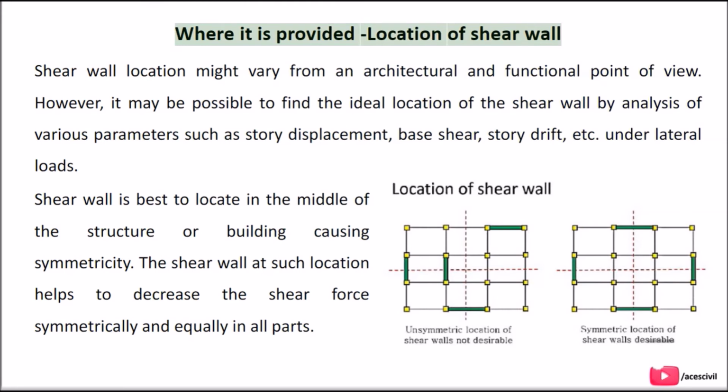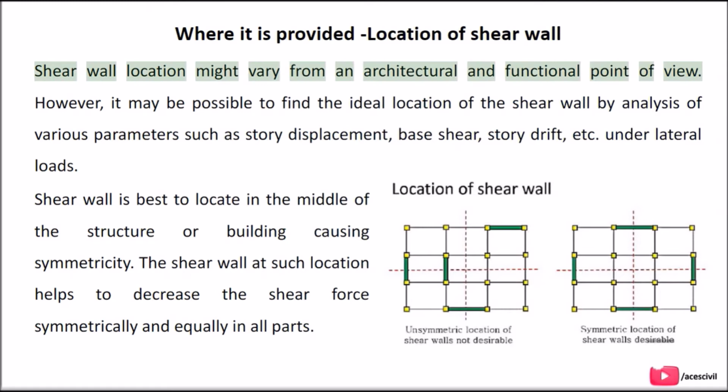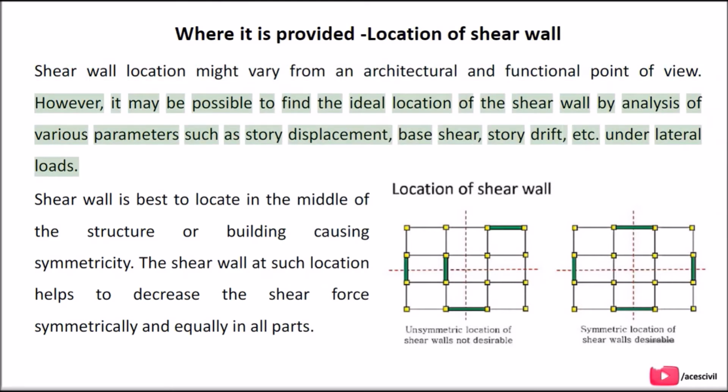Location of shear wall. Shear wall location might vary from an architectural and functional point of view. However, it may be possible to find the ideal location of the shear wall by analysis of various parameters such as story displacement, base shear, story drift, etc. under lateral loads.